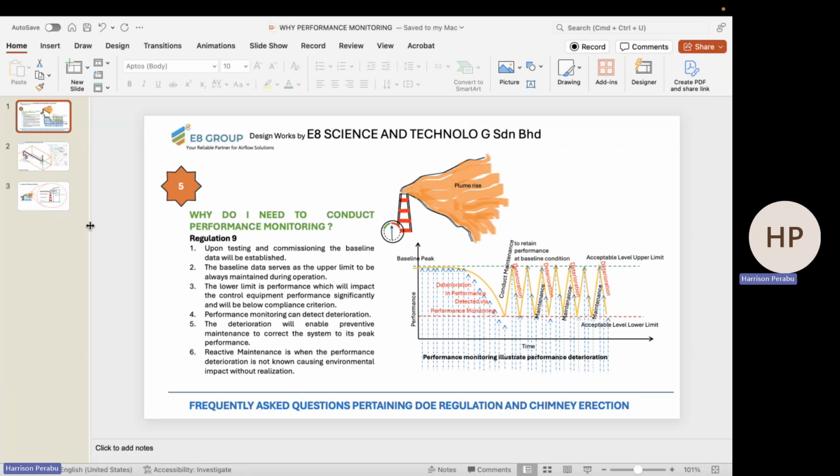The design flow rate is what is going to serve as the force, the flow rate which will convey transport velocity in the ducting so that condensation doesn't take place, so that settlement doesn't take place. That same flow rate is what is going to be used to size your filter so that we have an adequate filtration velocity and enough retention time so that the airborne contaminant can be captured at the filter surfaces or at the filter depth or the filter bed.